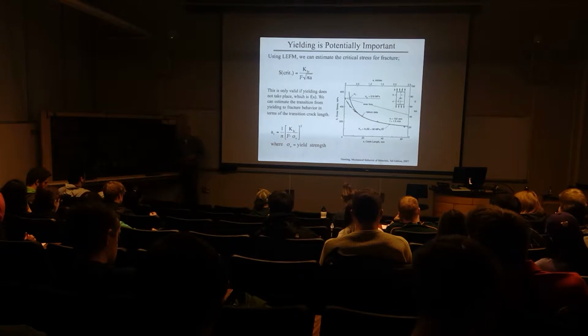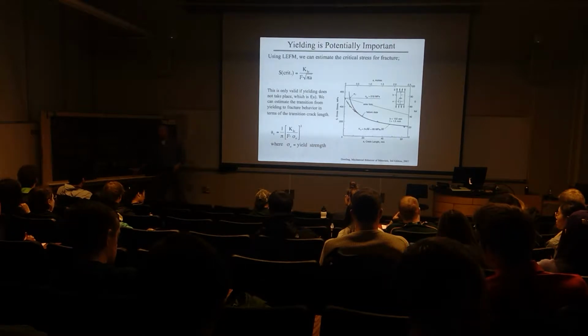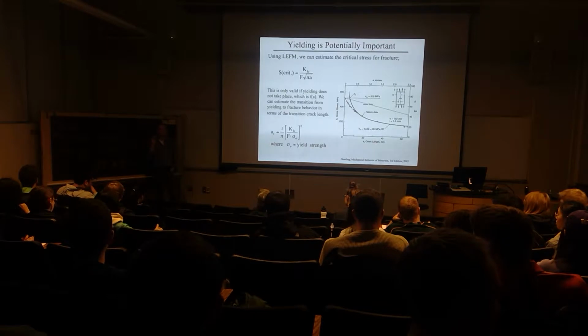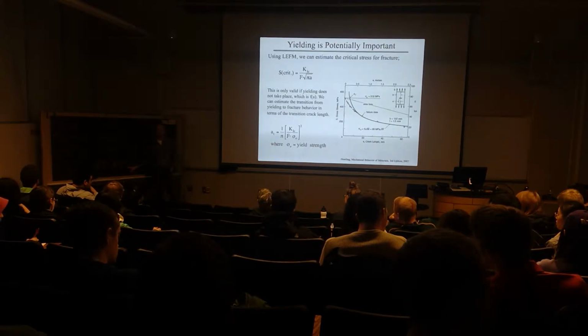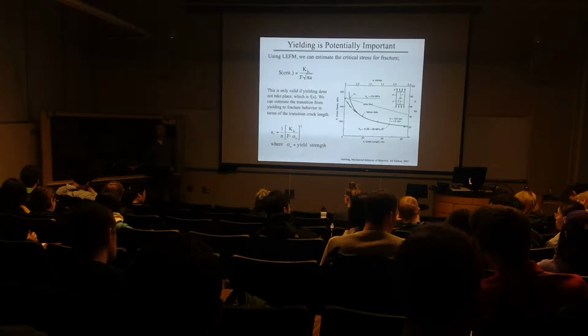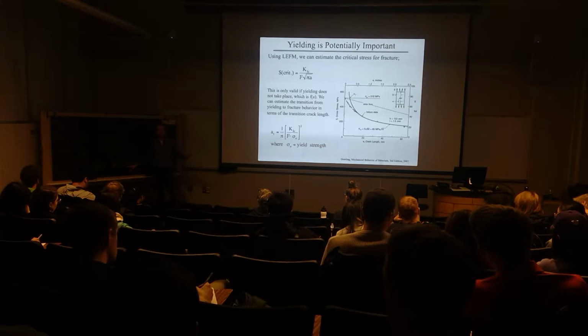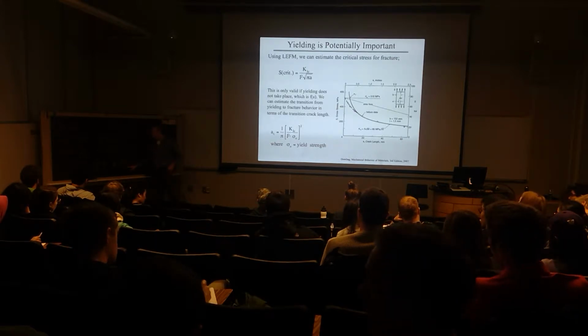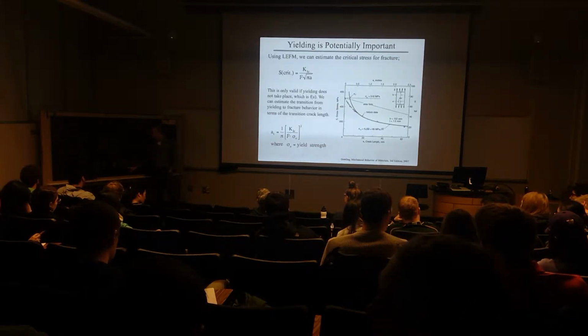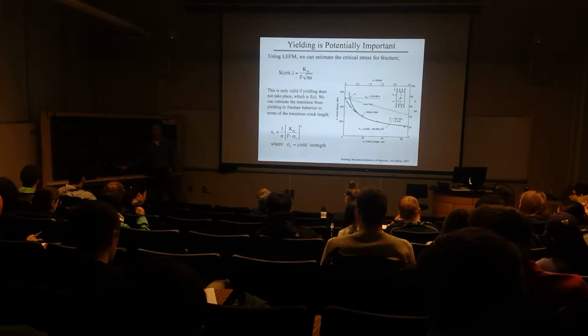The point of this course is failure analysis. So I want to think about how I can use this particular criterion. Let's say that I have a structure, I can see the fracture surface, and I can actually measure what the flaw length is. Okay? So I can determine the transition between stable fracture, a fatigue crack, let's say, and then unstable fast fracture. So I have this value, and from that flaw geometry, I can get the value of F, the geometry factor.